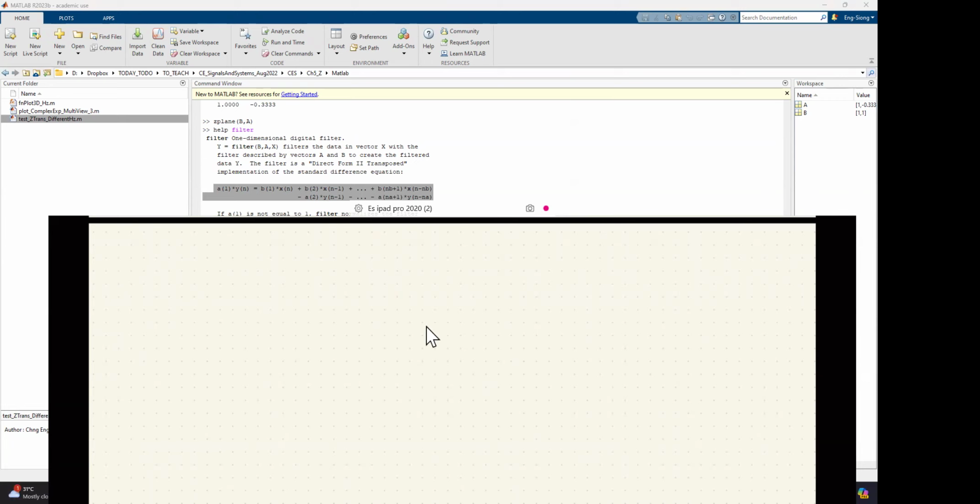What was our equation? y[n] equals x[n] plus x[n minus 1] plus 1 third y[n minus 1]. Now, where are the B's and the A's?